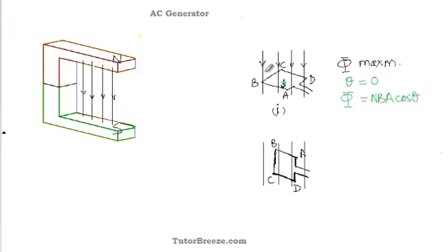But now if you notice, as this coil rotates in this direction, the anti-clockwise direction, for this position the change in flux, d phi by dt, is very small. So since the change in flux is small, the induced EMF is less, and at one position it is 0.